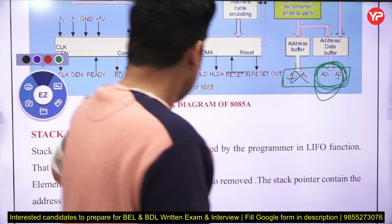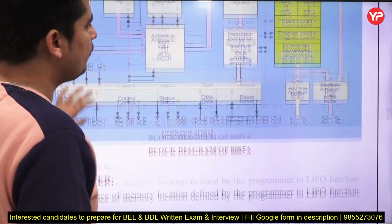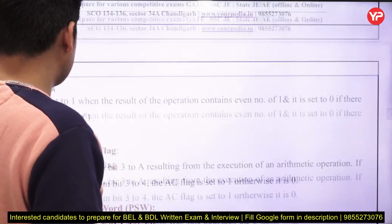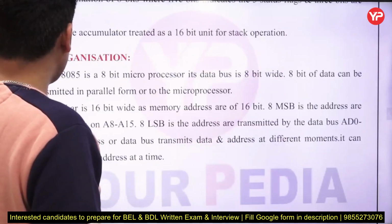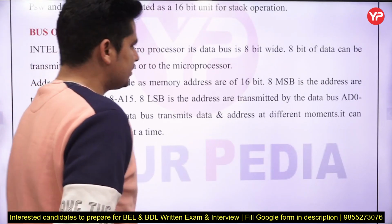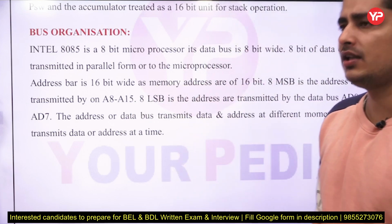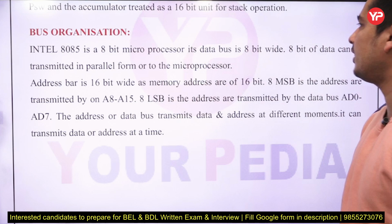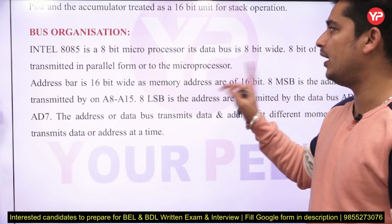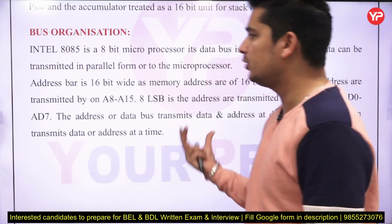So there is a term called address latch enable, which will decide whether we are doing the address fetching or the data transfer. That is the use of this one. So come back here, the bus organization in the 8085 8-bit microprocessor. That's why we call this an 8-bit microprocessor, because here we have an 8-bit data bus, right? 8 bits of data can be transmitted in parallel form to the microprocessor.